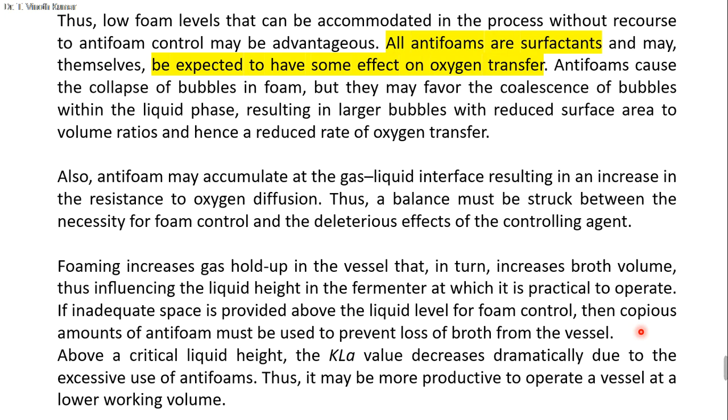And if you are using the liquid till 900 ml or 950 ml, there is no space to breathe. So the sparger has to give the air bubbles, and the air bubbles should reach the top. At the same time, some foaming may be formed in all the fermentation processes. So we have to leave space for the foam. That is why 30% of the fermenter vessel should be given for the foam settlement, and the foam can be easily controlled by using anti-foaming agents.